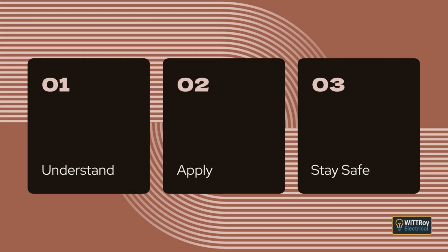Clause 2.5.7.2.2, Safety Service Circuit Discrimination. Clause 2.5.7.2.2 focuses on safety services. These are installations that must keep working during an emergency, such as alarms, evacuation systems, and some lighting. For these circuits, discrimination must ensure that a fault on a normal circuit will not interrupt the safety service. Likewise, a fault on the safety service circuit must not cause loss of supply to other safety circuits. The design must protect the function of these essential systems, even during faults.